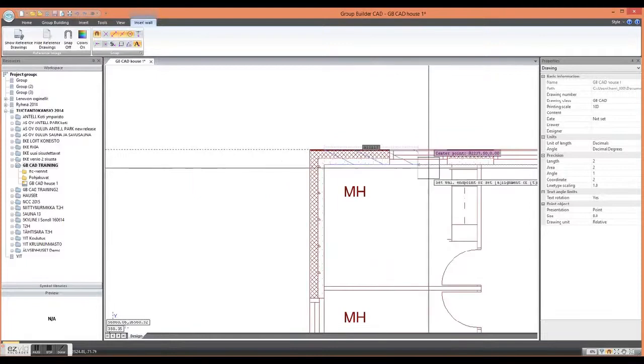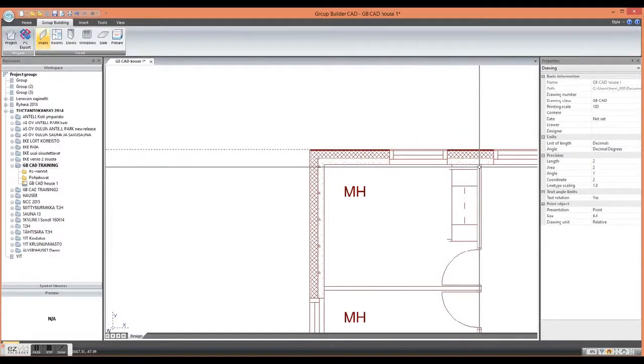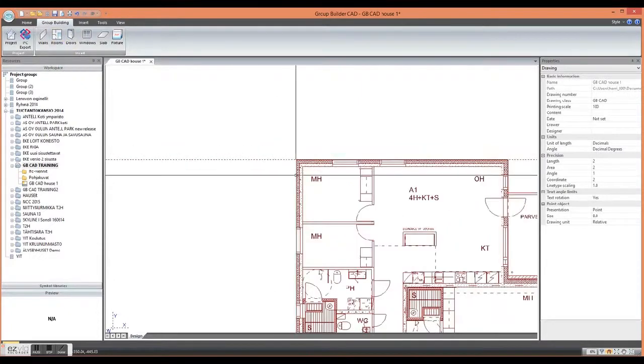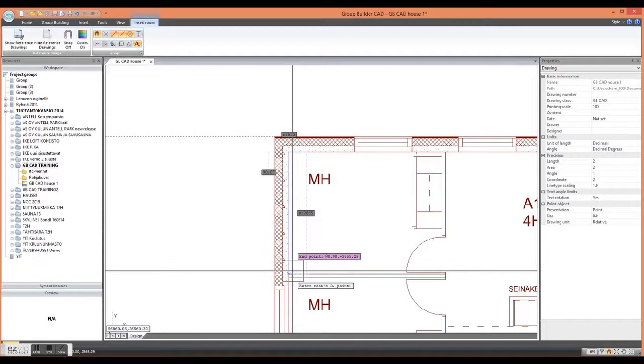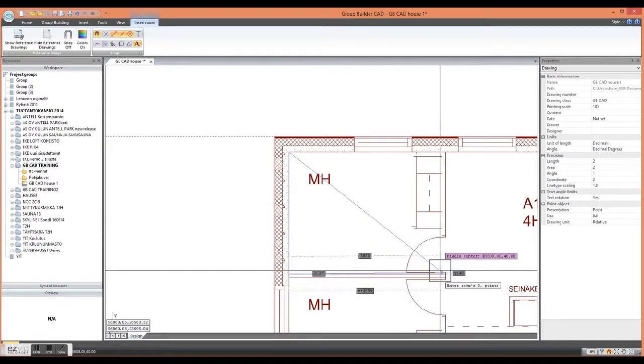By using the letter T, you can adjust the thickness, and by letter A, you can adjust the alignment of the wall. After you have drawn all the walls, we only did one wall and deleted that in this example case, you start drawing rooms.